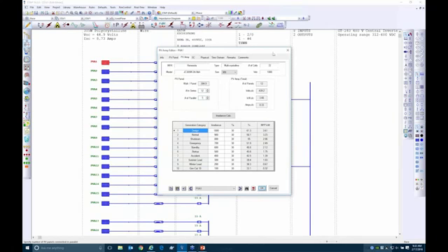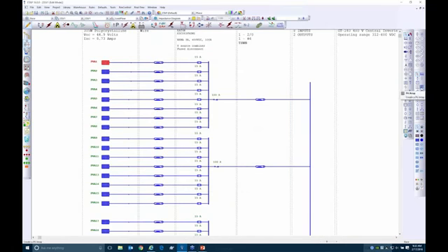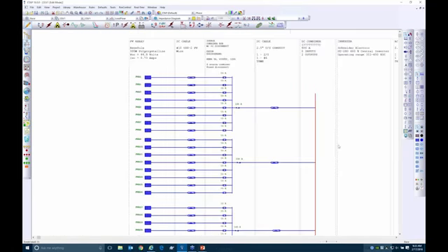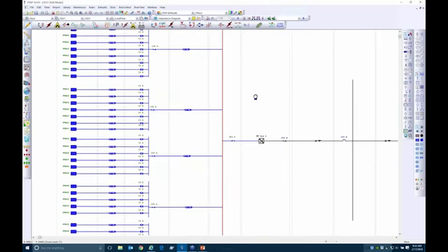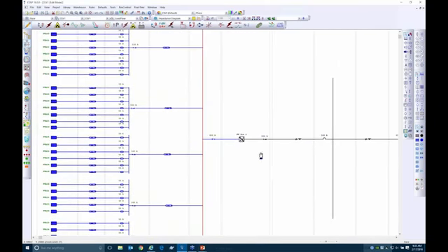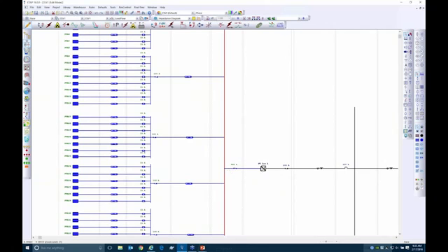There's no inverter option here because this is a DC element, and this element you can find from the PV array toolbar here, the DC toolbar, and you can drag and drop that into your model. But from the PV array, I have my string cable, which has its own individual fuse going to the combiner cable, and this bus essentially represents the combiner point inside the inverter.